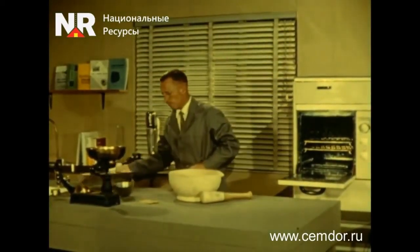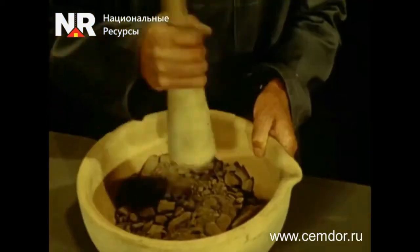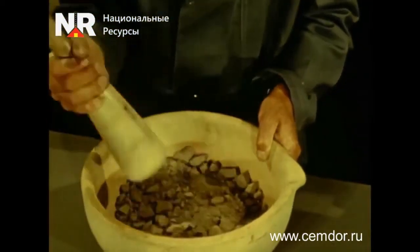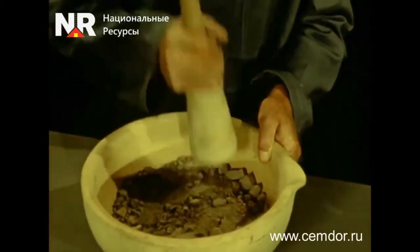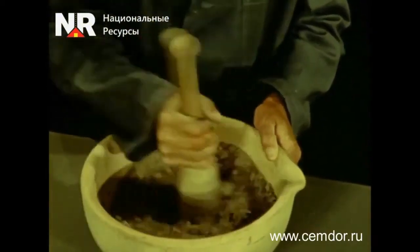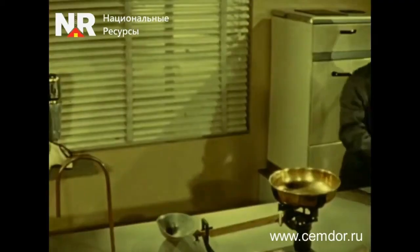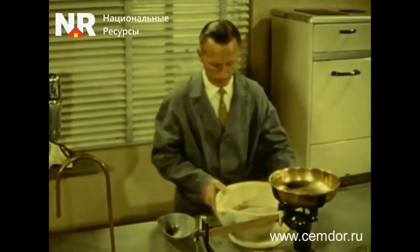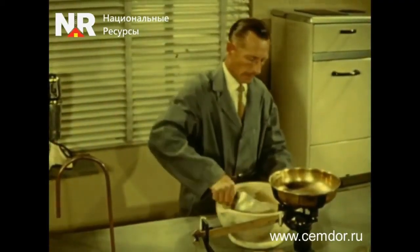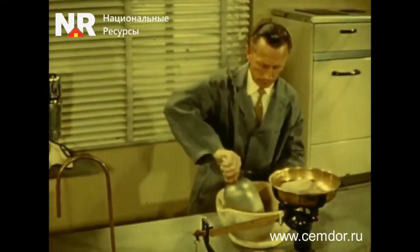After drying the sample at a temperature not exceeding 100 degrees Celsius, the soil aggregates are crushed. Next, a soil sample of the specified mass is selected. The selected sample is placed in a metal testing cup.